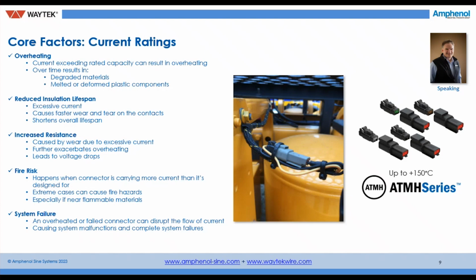System failure. An overheated or failed connector can disrupt current flow, causing system malfunctions and complete system failures. As an example of some of the ways that we try and mitigate that, we have over on the side one of our ATM H series. That H is going to stand for high temperature. There we're using thermoplastics that certainly go up an additional 25 Celsius to help mitigate those risks, often in those high temperature environments, but also caused by inaccurate application in regards to current ratings.